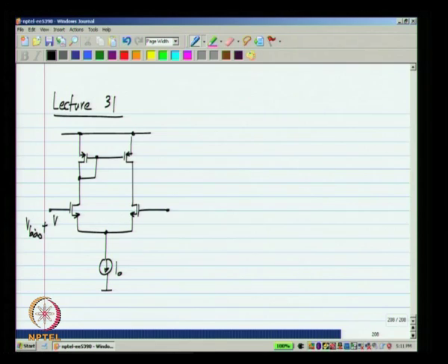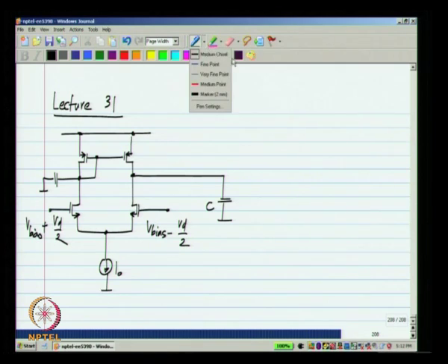We have purely differential input, and this is loaded by a capacitor. We have really only one parasitic capacitance of consequence, because the tail node incrementally is not swinging, it has a tail node increment of 0. So, we have only the CD3, which consists of parasitic capacitances from all the transistors connected to that node.